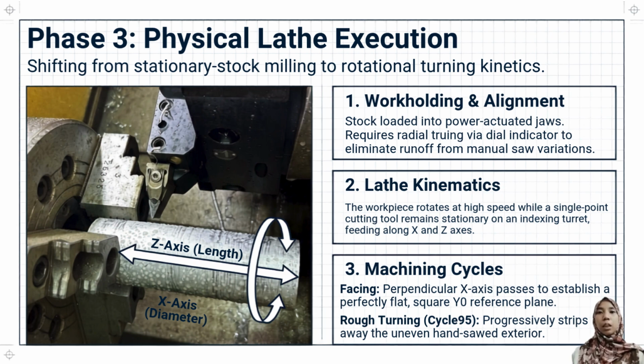Although the machining process follows the programmed toolpath, several real-world factors influence the final result. These include variance in raw material, cutting force variation, thermal effects, tool wear, and small measurement errors during inspection. These factors explain why the actual dimensions differ slightly from the simulation result.